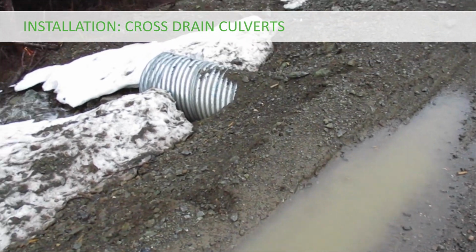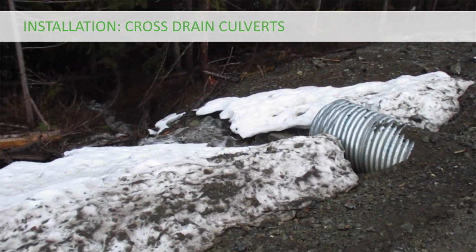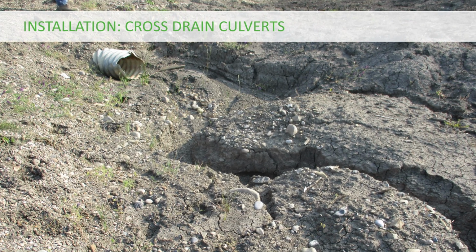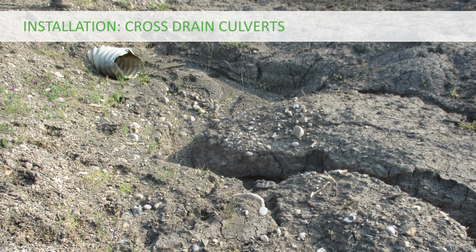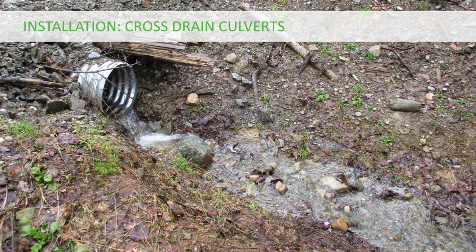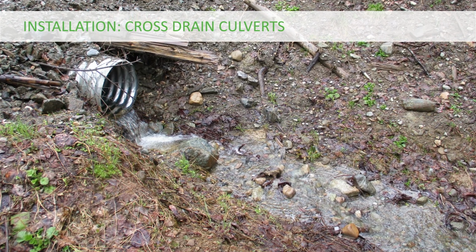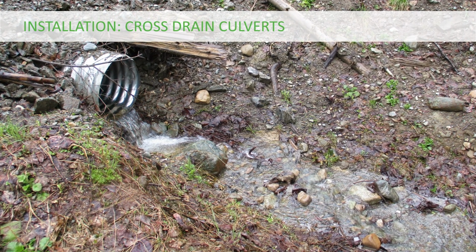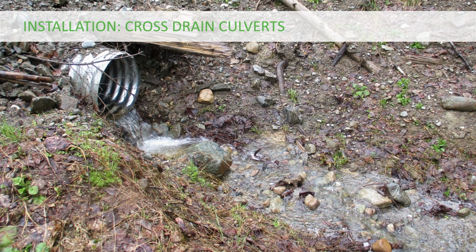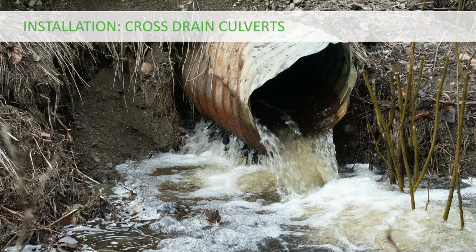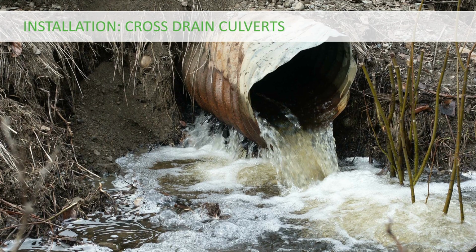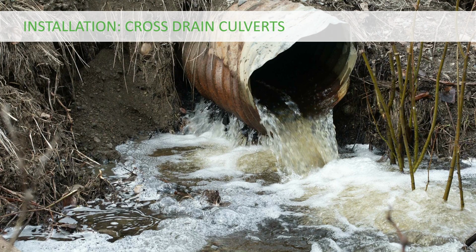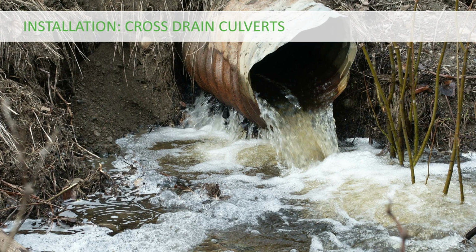High-velocity water flow can erode the soil below the culvert outlet and along the outlet flow path. Where high-volume flows are expected, or where erodible soils are present, consider armoring culvert outlets. Once outlet scour starts, erosion can accelerate and cause the road shoulder to weaken and fail. Over time, an eroded flow path due to high volume flows can take on the characteristics of a stream channel. This is often the case when there is an inadequate quantity of cross-drain culverts and too much ditch water has been directed to a singular culvert installation.